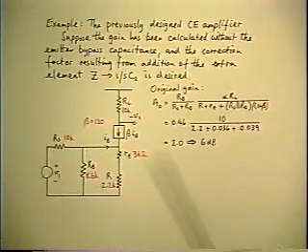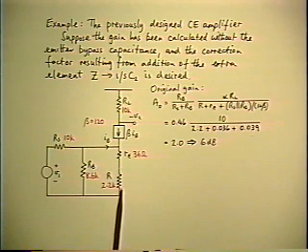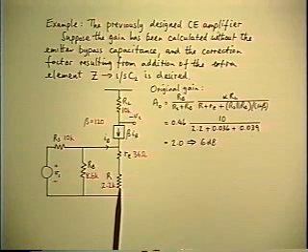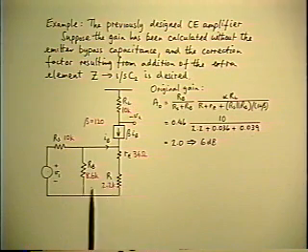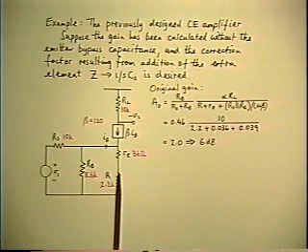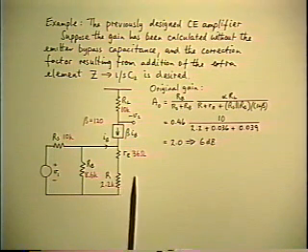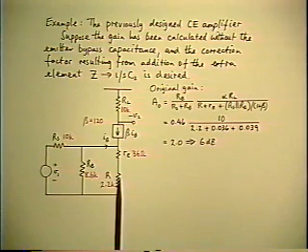Now let's imagine that we've done all that horrendous amount of work, and we decide later on that we want to add something to the model. In particular, let's add the bypass capacitor around this bias stabilizing resistor. And even though in this example, obviously, it wouldn't be that much work to go back and do it again, let's use a simple example to illustrate the extra element theorem. So, the approach is, we're going to add an element across R. And without knowing what it is yet, all we have to do is calculate the two driving point impedances seen across those terminals.